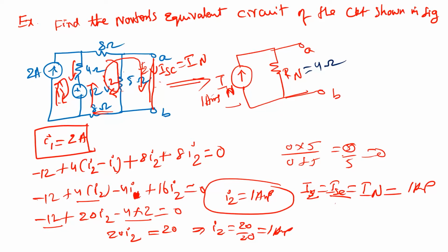This is the total equivalent circuit. Right. Suppose you want to find, for any resistance I have connected here, that short circuit current or how much current is flowing through the 2 ohm. So how are you going to find it? Right. So you just apply the formulas and we can find it. Right. So to find the current flowing through the resistor, you can apply the current division rule and we can find it.